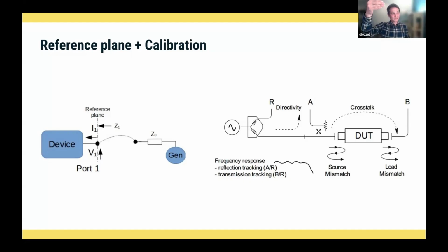So how do I both tell the device that the thing I want to measure is actually 2 foot down the coax, and the coax is a little lossy? Sorry, I didn't spend a huge amount on it, so we're going to lose a bit of power getting to and from the device. And it's got distance, so that sine wave is going to shift in phase from where it is at the edge of the NanoVNA or the VNA port to where it goes out.